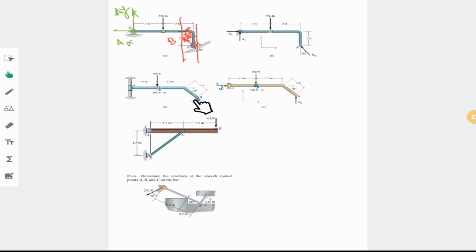And at point B it's clear because we can have motion in this direction, but not in the vertical direction, and that's why we have NB, which is a normal force at B. And for considering the motion that I'm mentioning a lot, you just need to consider a portion. Don't consider the whole structure. It would be completely confusing. But if you cut this and just try to move the single piece, a small piece of this, you can do motion in vertical. You cannot do motion in horizontal direction, and you cannot rotate it, and that's why you got these two values over there.